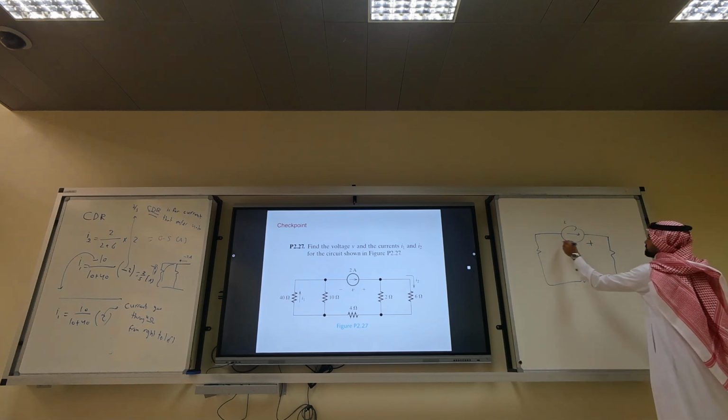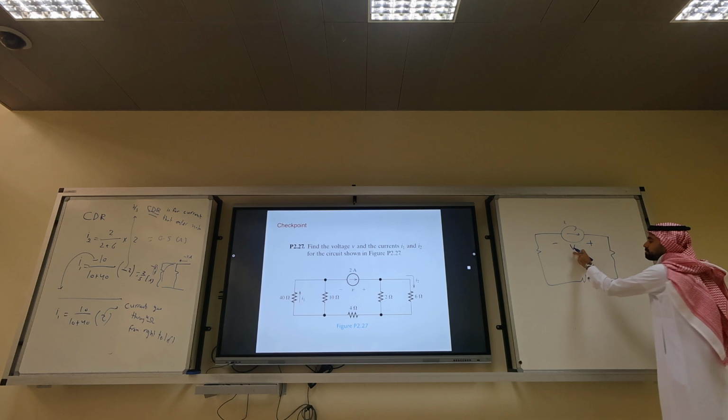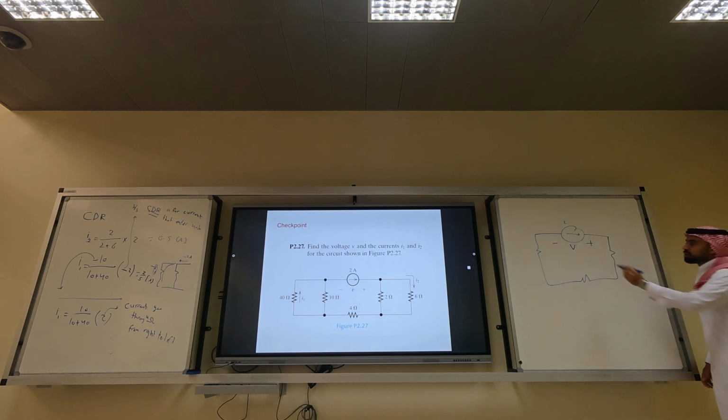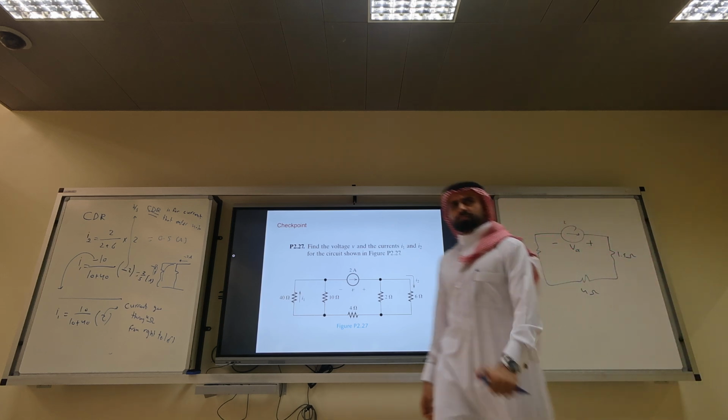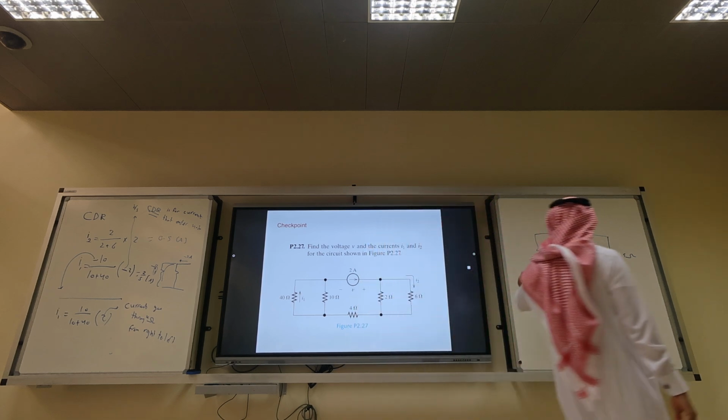And then I have plus minus V, you can call it V, you can call it V current source. It's up to you. What is the resistance equivalent? 1.5 ohms. Keep the 4 here. And 10 parallel with 40? 8. Are you sure? 8.